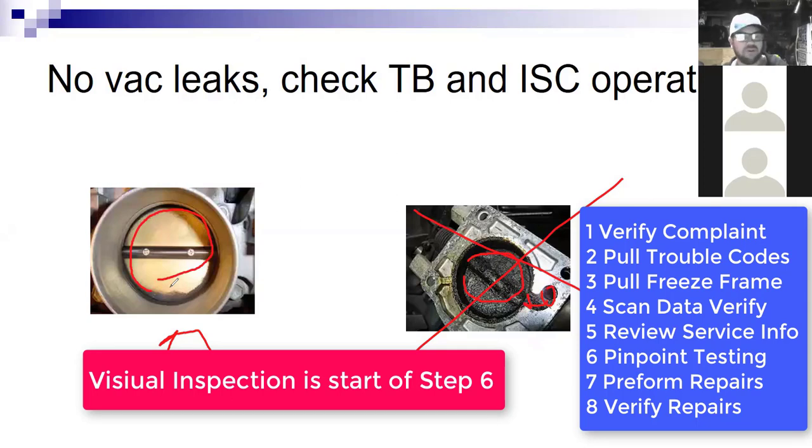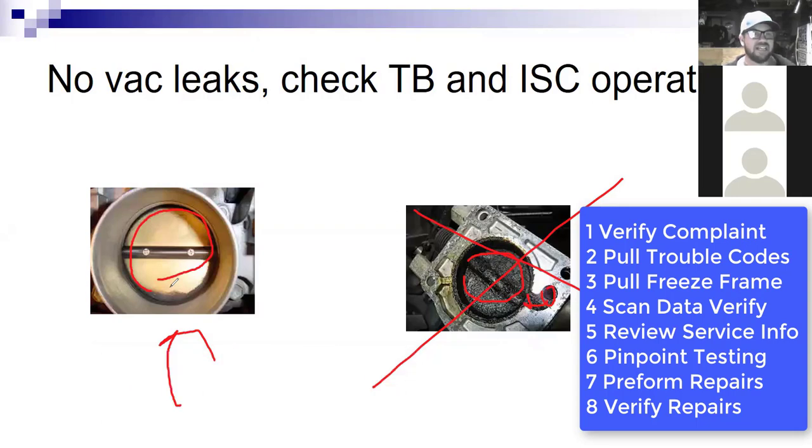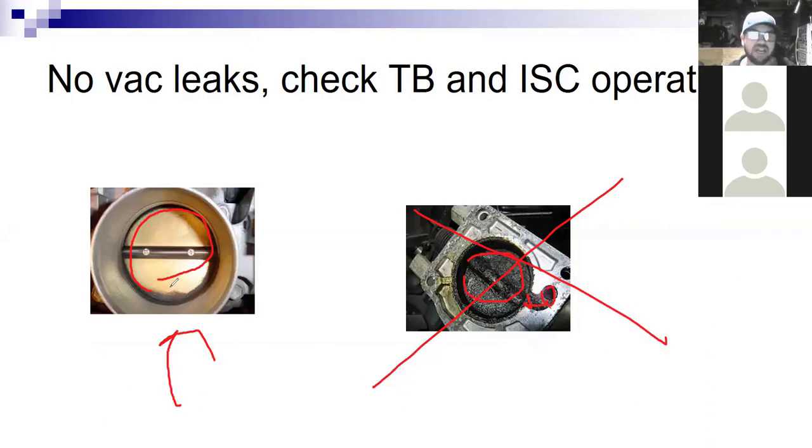Unfortunately, I didn't get more information, more data from the student. I would have liked to see some scan data with some fuel trim numbers. I would have liked to see the freeze frame information. All that could have gotten us further in this diagnosis. But I at least wanted to share this with you to show you how I would approach this